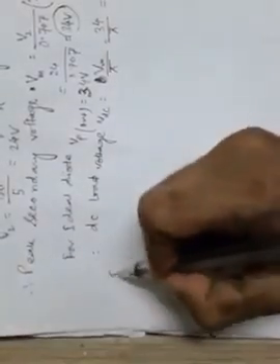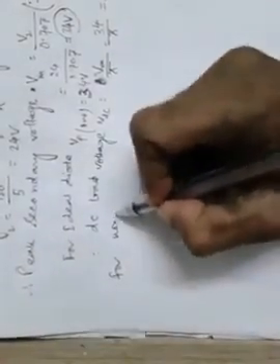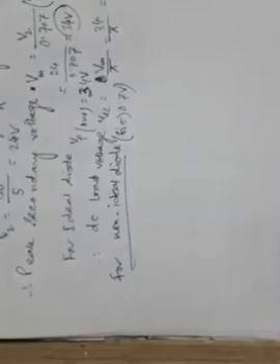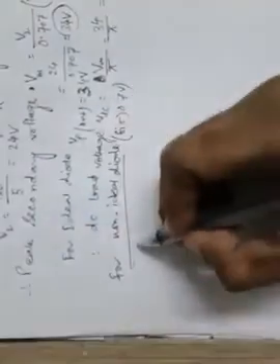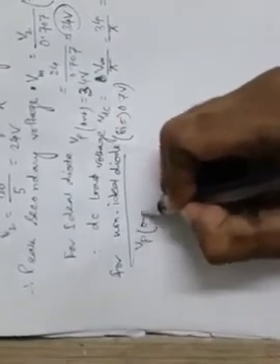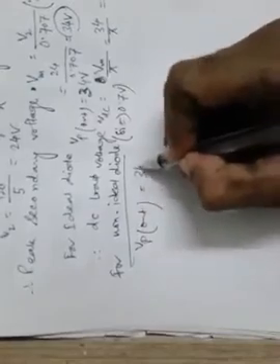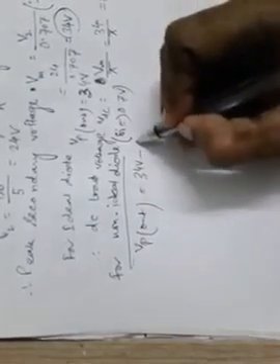Now if it is a non-ideal diode, considering the second approximation, that means considering a silicon diode with cut-in voltage of 0.7 volt, if we incorporate this data in the calculation, then Vp out, the peak output voltage or peak load voltage, will be 34 minus the drop of barrier potential, that is 33.3 volt.